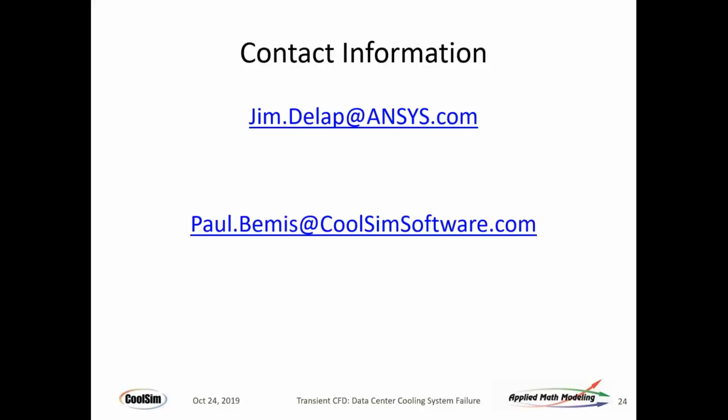The next question is: is it possible to do a transient CFD analysis on a site that uses a DX and dual fluid evaporator solutions at the same time? A little more difficult. That is a situation where you've got both mediums in the cooling unit. This often happens. They put gas in there. They also put liquid in there. It's in the box, inside the unit, in the room. Again, all you have to do is decide which one you want to fail, if you want to fail them both. The DX, again, is fairly simple. If it fails, game over. If the chilled water fails, then, are the pumps running or not? Same set of questions. Effectively the same scenario that we just talked about.